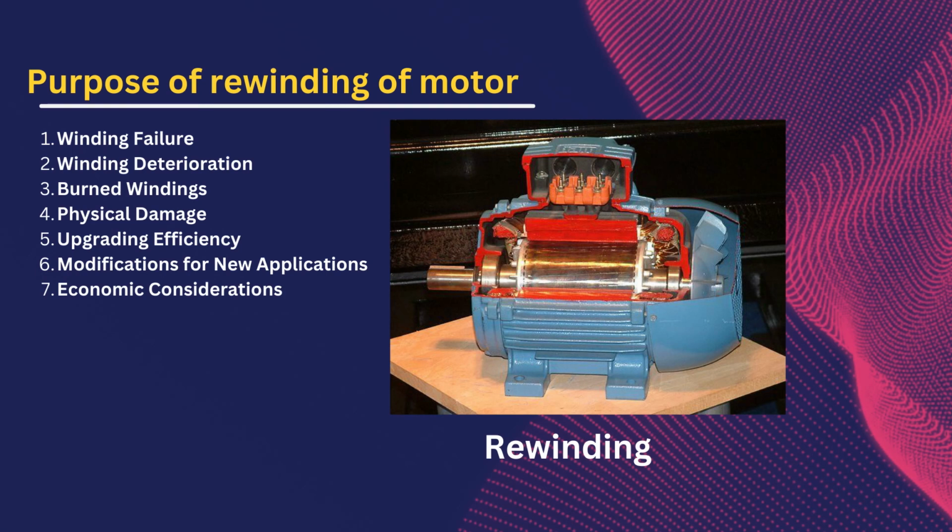These faults can be caused by excessive heat, voltage spikes, overloading or aging of the insulation. Rewinding replaces the faulty windings, restoring the motor's electrical integrity.